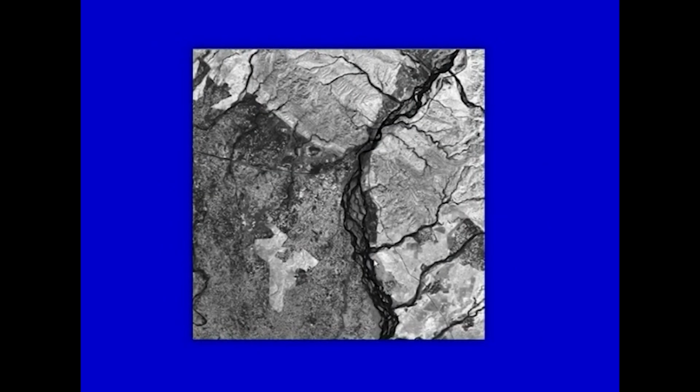Here we can see the ratio image of a particular area. The bright portions in the image show the vegetation content being much greater than other information such as water bodies and river courses, which are having low reflectance and they are depicted in dark tones. So, by undertaking the process of ratioing, we have now been able to segregate the healthy vegetation from all other information as it is being depicted in the bright tone in the image.